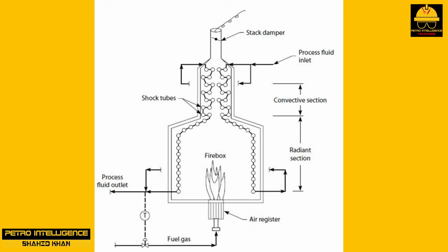This sets the heater up for afterburn in the stack, and the heating value of the fuel is also effectively reduced. Allowing a fired heater, boiler, or furnace to operate with insufficient air is hazardous because the products of incomplete combustion are hot and will ignite as soon as they find sufficient oxygen. This usually results in afterburn in the convective section or stack and can even lead to explosive detonations. The products of partial combustion are atmospheric pollutants. It is not possible to operate an automatic temperature control on the wrong side of the point of absolute combustion.